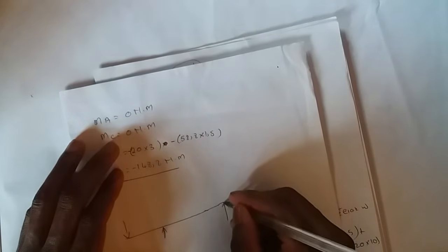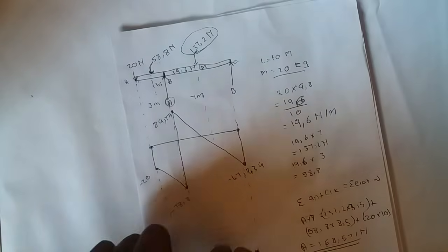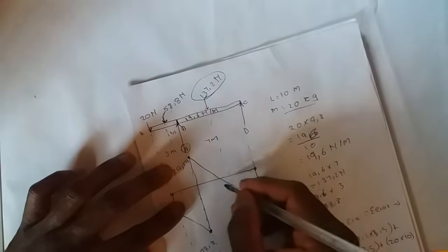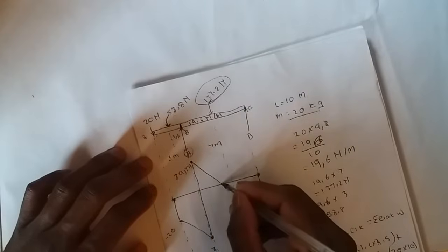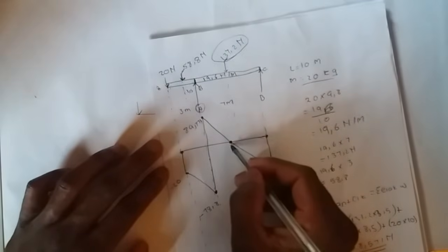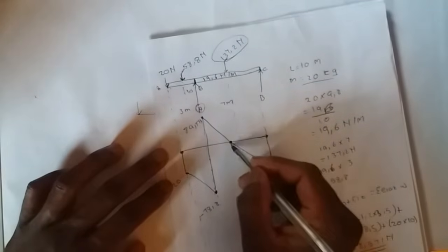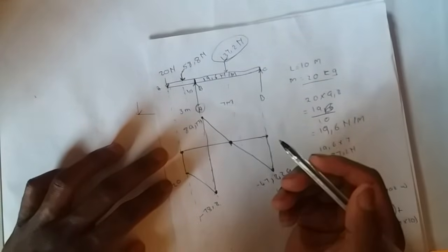So we have a beam like this. This is our beam. One thing we know about the maximum bending moment, which will be the turning point of this, is that it will occur where our shear force diagram cuts 0, which is this point. But we do not know the distance from this point to this point, so that we can calculate its moment, which will be the maximum bending moment.